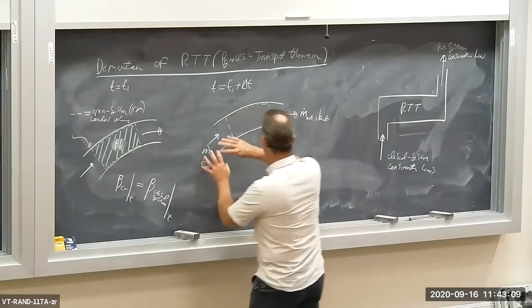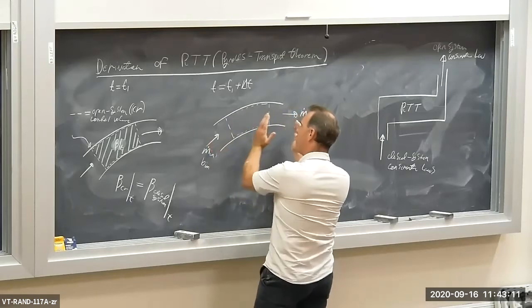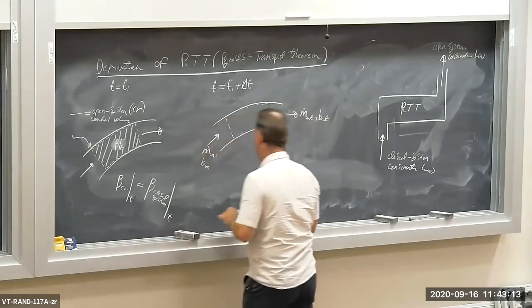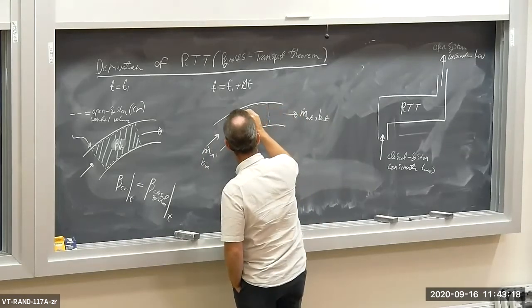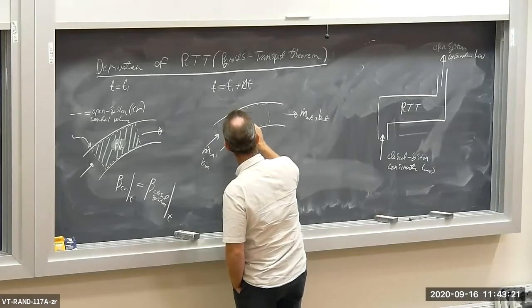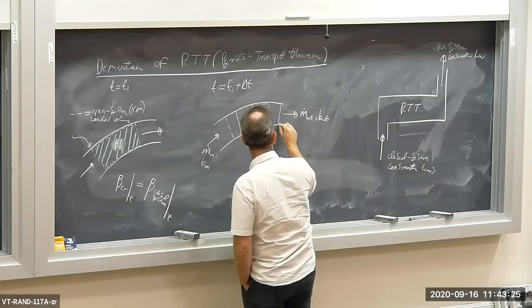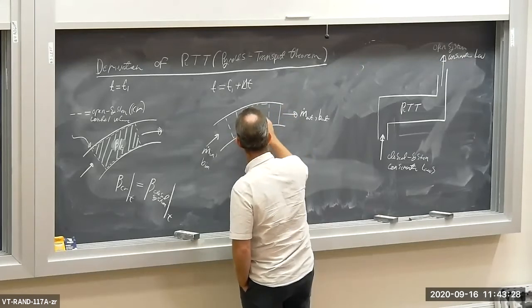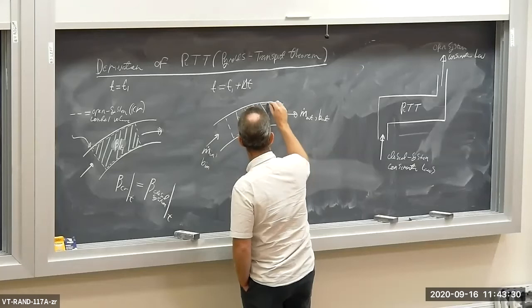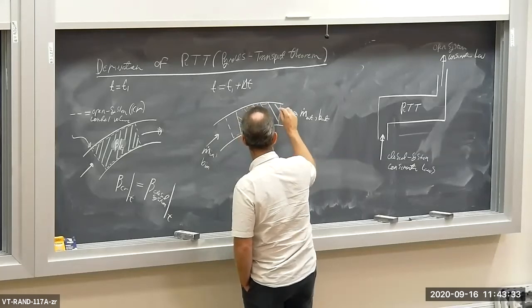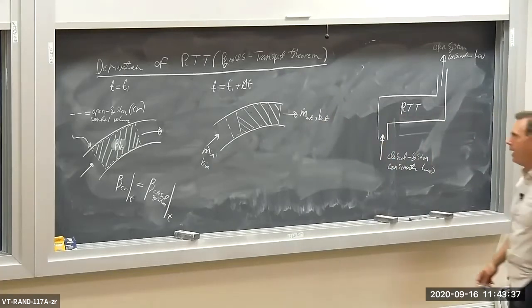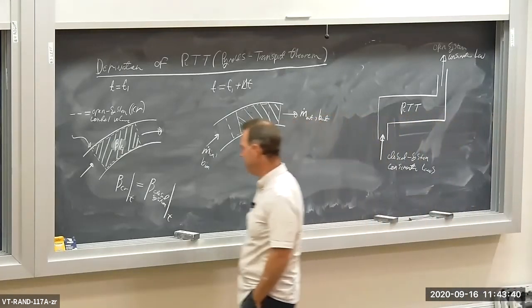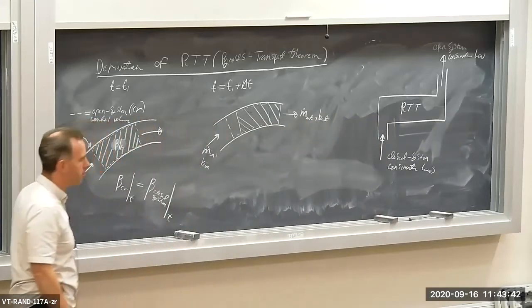Now, because the mass is flowing in and out, my system is getting pushed through the control volume. So at some time t1 plus delta t, the system, my cross-hatched closed mass system, has now been forced through in and out partially of my control volume. So that's what the system, closed mass system, looks like at time t1 plus delta t.